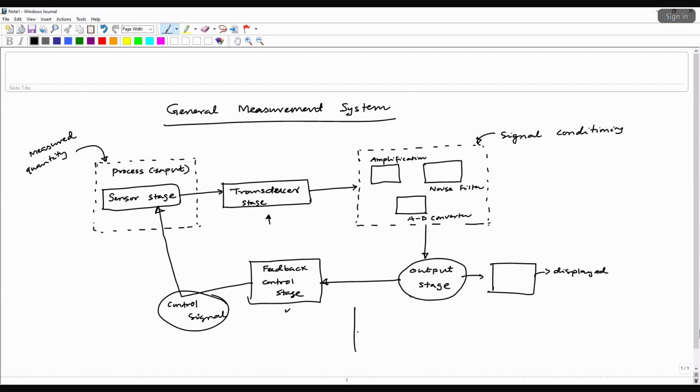So that is a typical system that you see, right? If you have set 80 degrees centigrade, the temperature basically shoots up and then it slowly oscillates and then finally reaches 80 degrees centigrade. So to achieve these kinds of processes, you need a control signal. Okay, so you can control what kind of input is coming to the process environment, so that the environment is controlled, or your process is controlled.